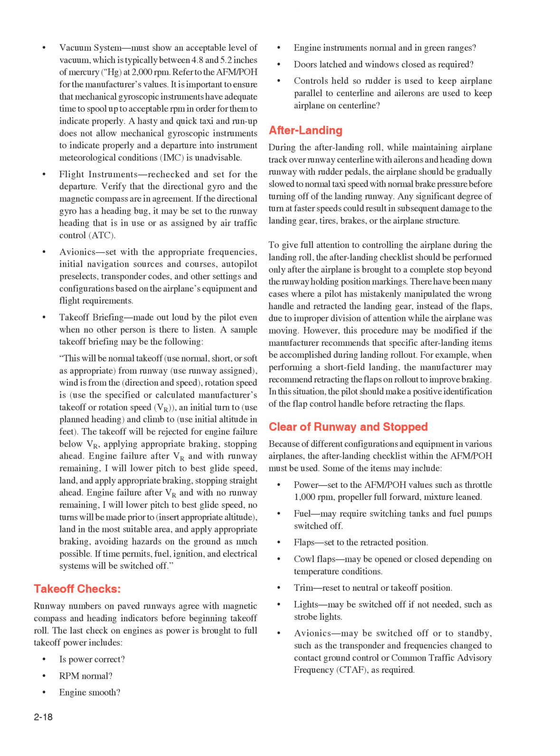It is important to ensure that mechanical gyroscopic instruments have adequate time to spool up to acceptable RPM in order for them to indicate properly. A hasty and quick taxi and run-up does not allow mechanical gyroscopic instruments to indicate properly, and a departure into instrument meteorological conditions, IMC, is unadvisable.